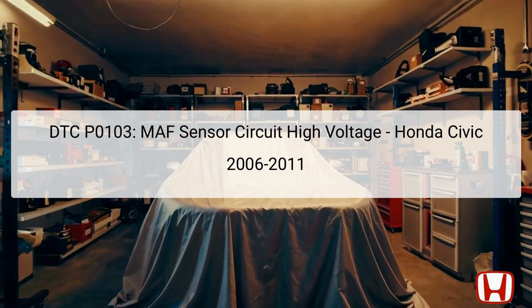Welcome to the troubleshooting presentation for DTC P0103, which indicates a high voltage in the mass airflow MAF sensor circuit. This diagnostic trouble code is pertinent to the Honda Civic models from 2006 to 2011.